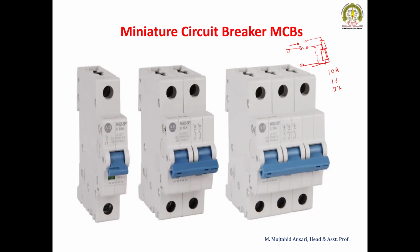But the MCB has an equal characteristic, and you can use it repeatedly. Once there is a fault, it is going to trip out, and once it trips out, we can again switch it on. The meaning is that there is no need to replace wires in MCBs. So there is the single pole MCB, the SP MCB, and it may be a DP MCB. It is used for phase and neutral, whereas in the single pole we are using only the phase wire and neutral is directly connected.